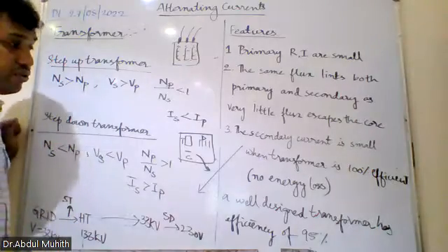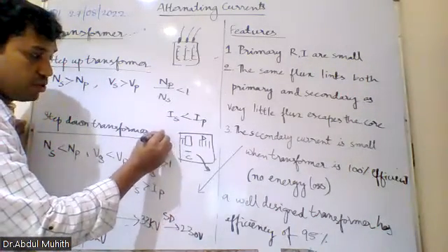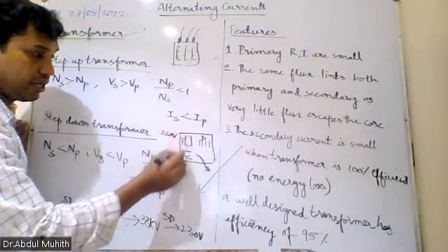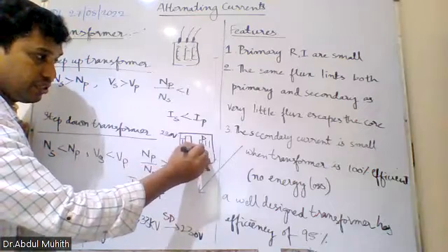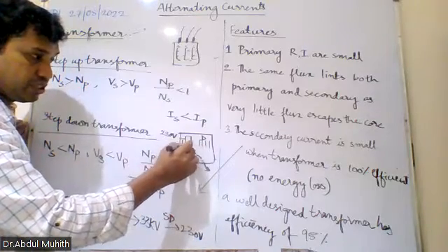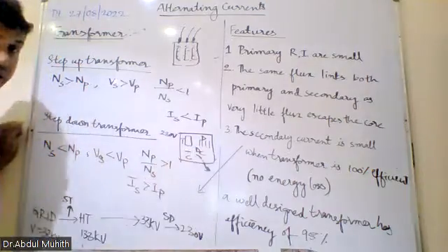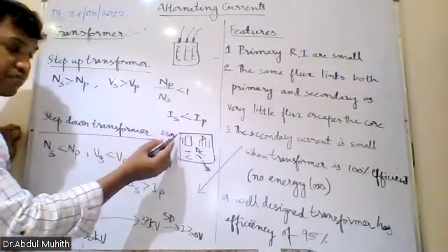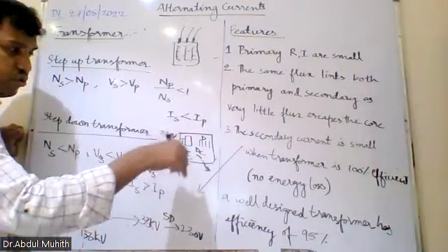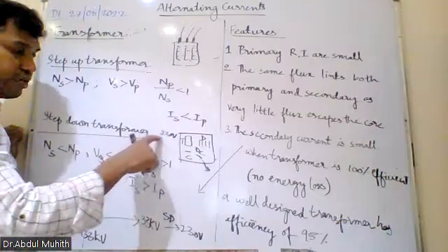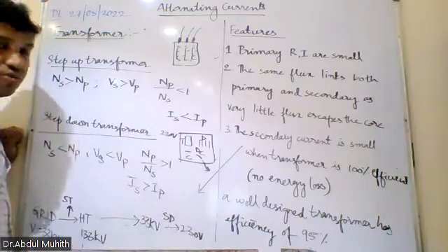That is how. See, the 230 voltage is there, no? The 230 voltage AC you cannot directly convert to DC. This transformer has to convert it to DC current. How can we do that? First, the transformer has to bring down the voltage. We have to use a step down transformer from 230 voltage. We bring down the voltage to 30 volt.